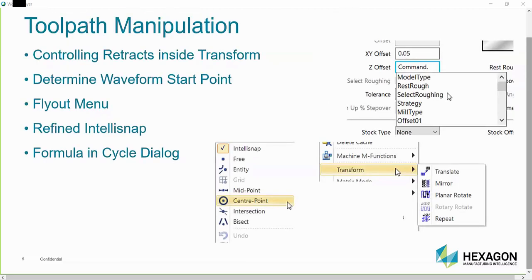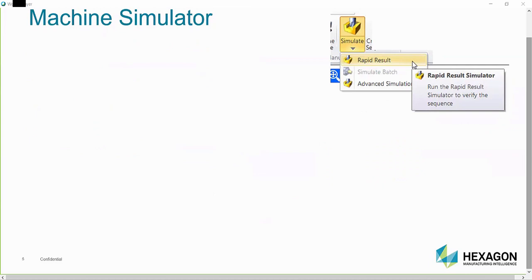Moving forward, we're then going to have a look inside the dialog boxes themselves, setting up a formula. This can be extremely useful if you just want to metricate something or calculate a feed and speed. Picking up a global modifier variable inside Edgecam and manipulating that variable.